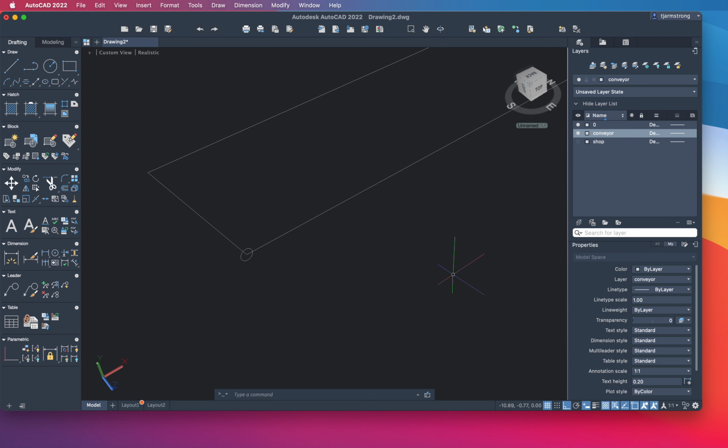So I'm going to use the extrude command, EXT, for extrude. I'll come back and select the circle, my cross section, and now I'll just start dragging it towards the other end. I can try to snap on this, or it's probably more reliable to just type 0.75, and there's my roller. And actually, let's zoom in a little bit.